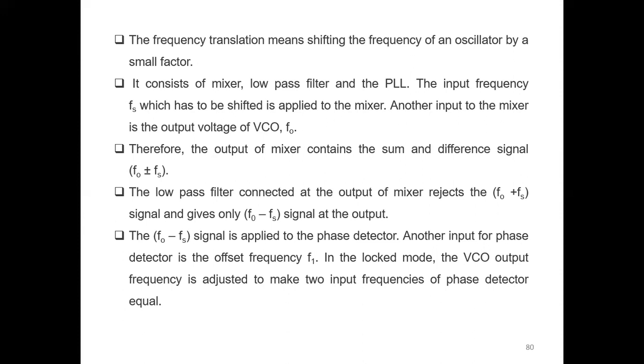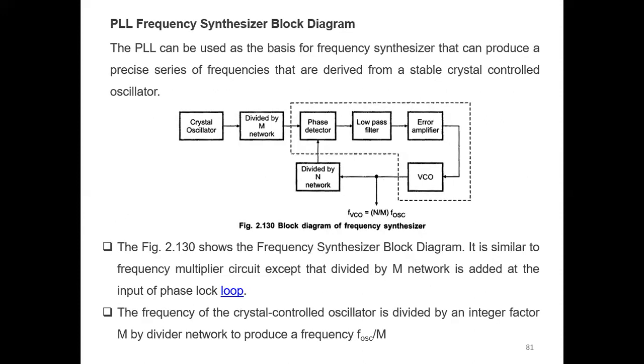In the lock mode, the VCO output frequency is adjusted to make the two input frequencies of the phase detector equal. Okay, so let's see the PLL frequency synthesis block diagram.